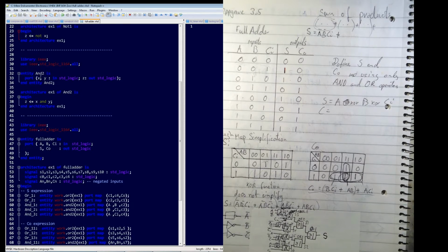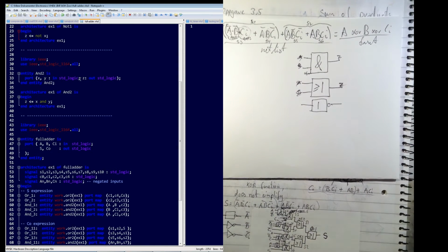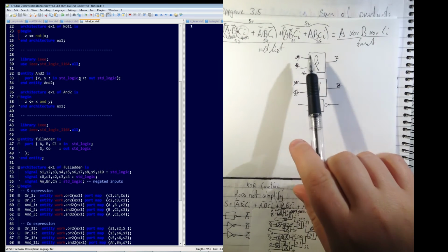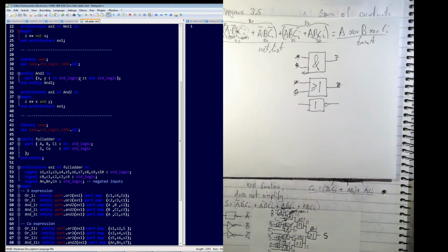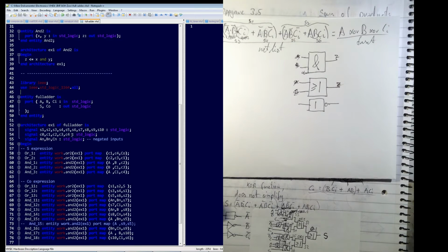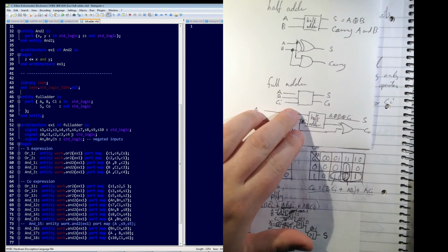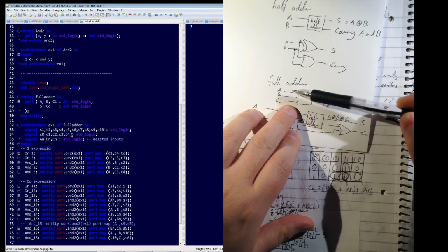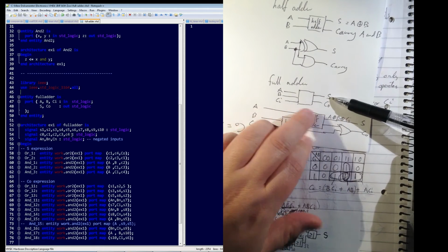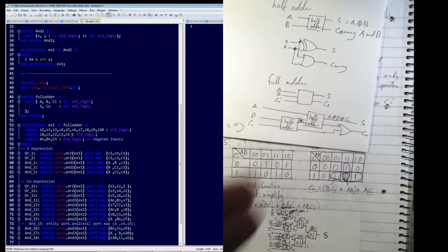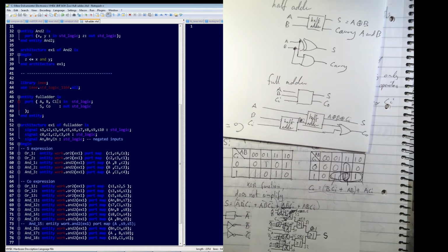So, and here we have the AND gate. It has two inputs and a set. So bring this in again. You see the AND gate. It has two inputs and then an output. So the output is X and Y. That's it. Now, if we're going to make the full adder, we need three inputs: A, B, carry in, and S, sum out, and then carry out. So that's what I have here. These are the inputs and these are the outputs.